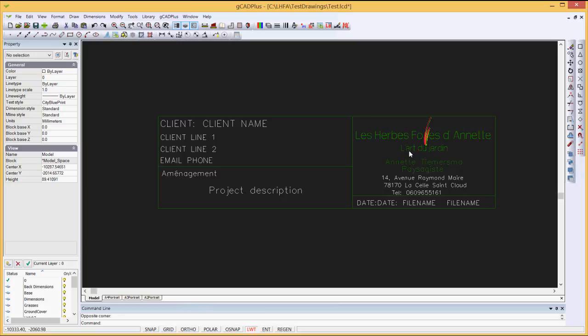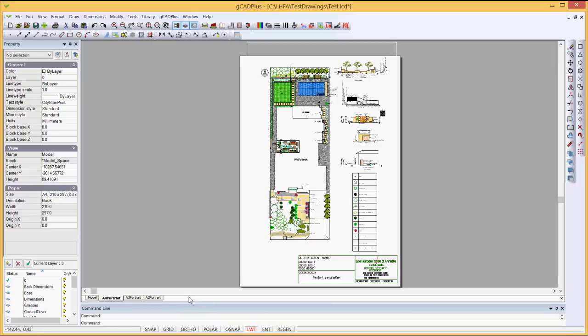I think it's an excellent idea to test your title blocks on various size sheets. If we move to an A4 sheet, here's our current title block, the one that we are developing on an A4 sheet. And it looks to me at first glance a little bit large. Notice that it's encroaching on our design a little. So if we do a revised version, we might want to try making it a little larger and maybe cramp things down on the right hand side there. Just reduce the height of the block.